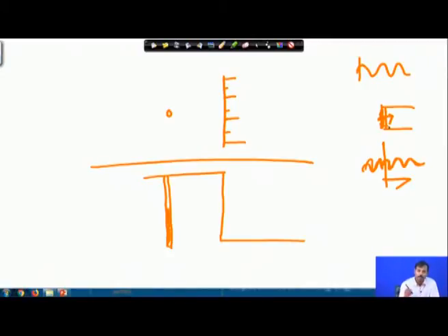Whenever you observe these blasting videos, you will find in the post blast drill mark a zone where the rock fails under compression, and this is called the crush zone or compressive failure zone. Okay. In this crush zone the rock fails under compression and that is why it becomes powdery.